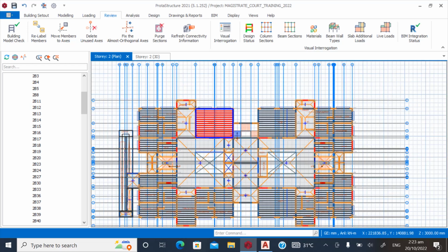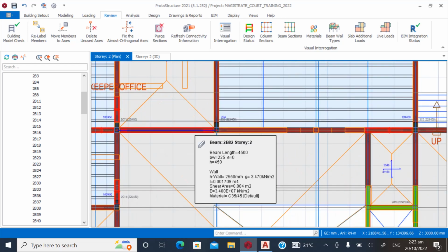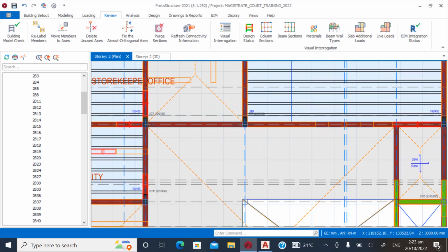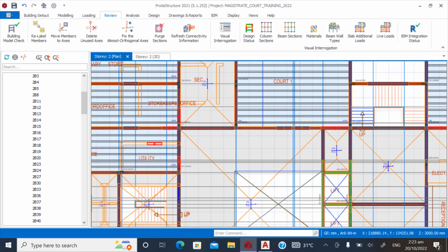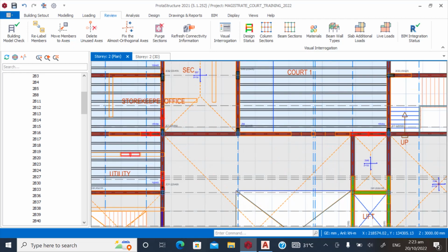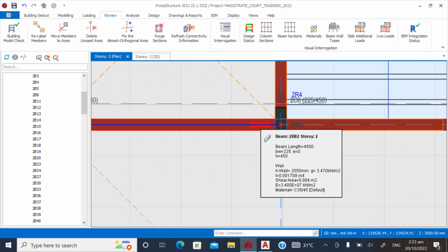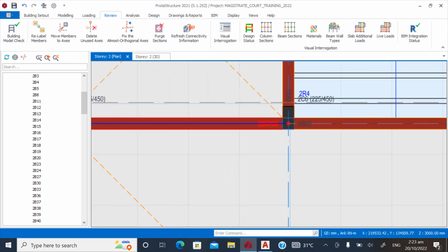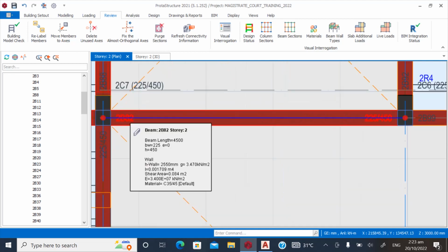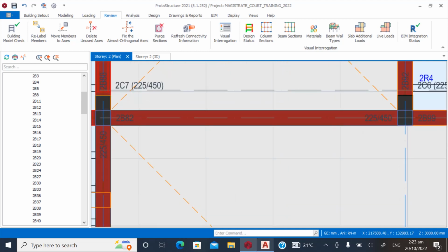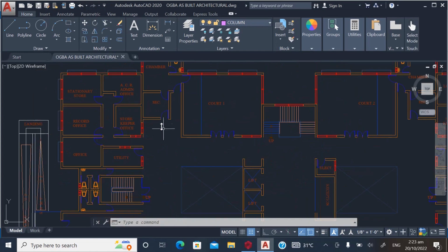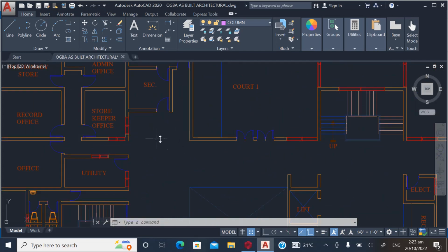But at the same time, if you want to delete walls from some of the beams that are not subjected to wall loads, you can actually do that by going to the beam like this. For instance, this very beam is not carrying any wall load. If you go to the architectural plan, the beam that runs across this area is not having any wall on it.